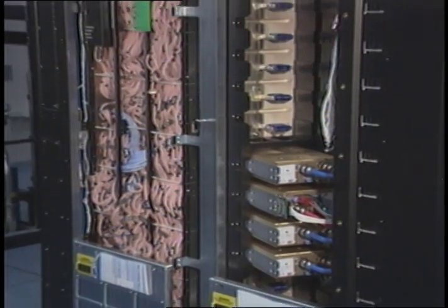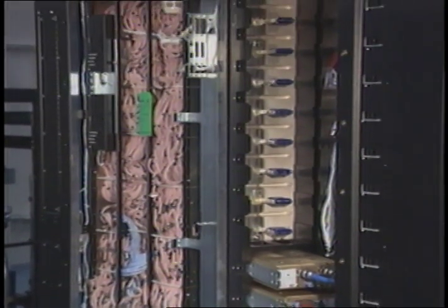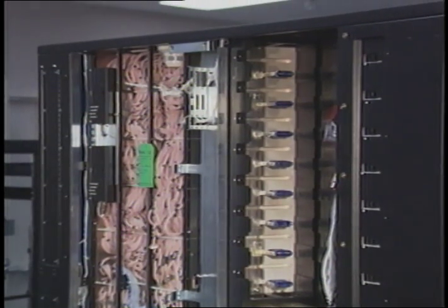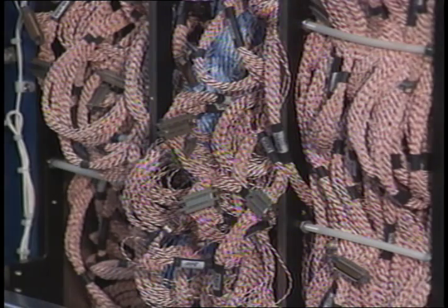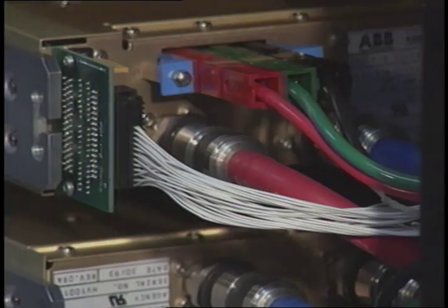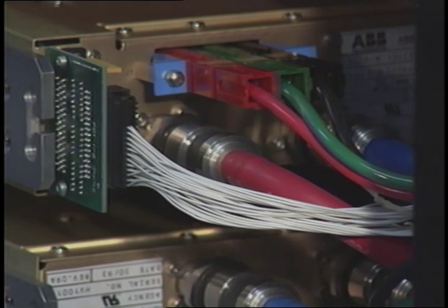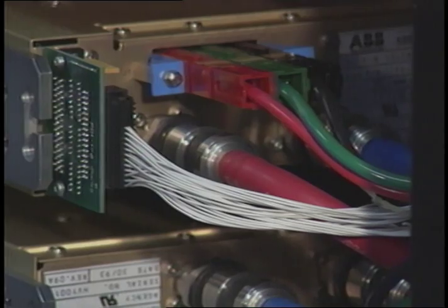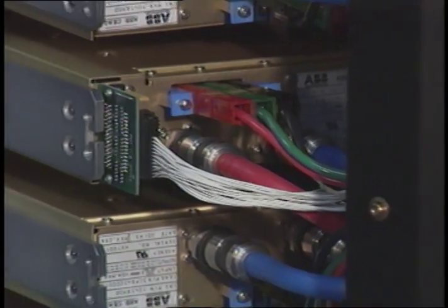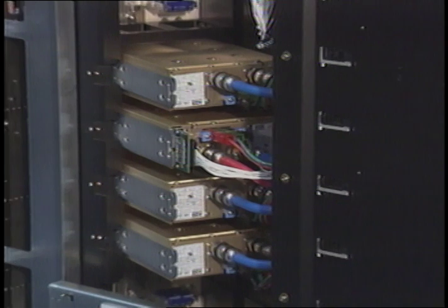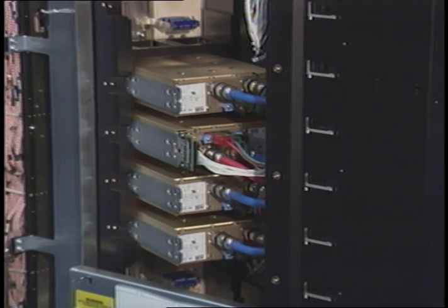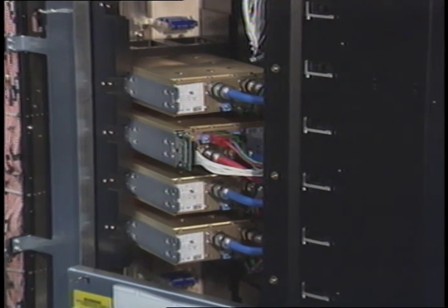Bundles of high-performance Teflon wires attached to the chassis connectors provide the toroidal communication paths. The arrangement of the wire bundles can be changed to support the future addition of modules into chassis which were initially configured to smaller sizes. Switching power supplies, each supplying up to 1800 amperes, provide module power. Standard configurations provide for one extra power supply for each required voltage, allowing additional fault coverage for the system.